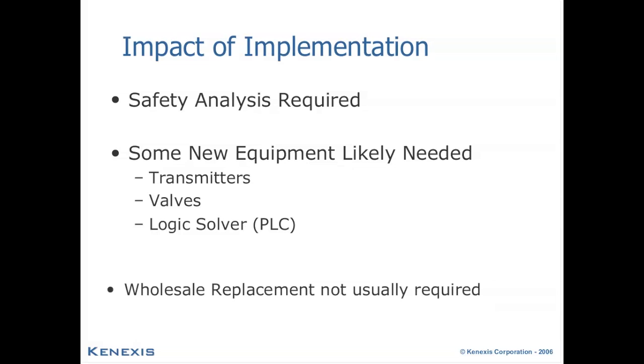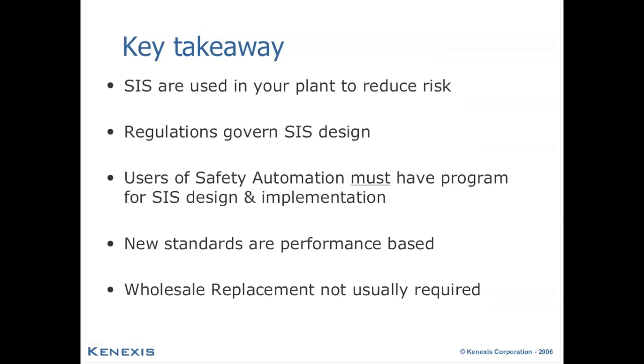In terms of the key takeaway of this overall presentation, SISs are used in plants to reduce risk, not in and of themselves, but through a combination of systems of administrative controls and other layers of protection that provide a sound basis for risk reduction.